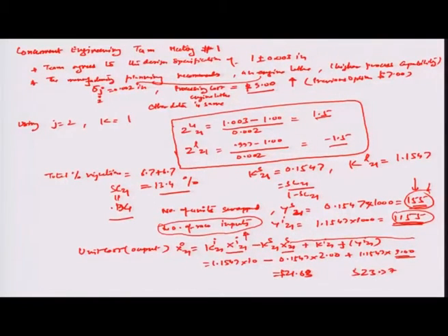In comparison to what was earlier, which was $23.97 in the serial engineering, you still see a decrease in the price of the output, even though the quality parameters have improved and even though the processing cost is higher in this particular case. The number of scrap coming out of the process has drastically improved, because of which all the additional cost which was being packed up in the turret lathe is now gone.